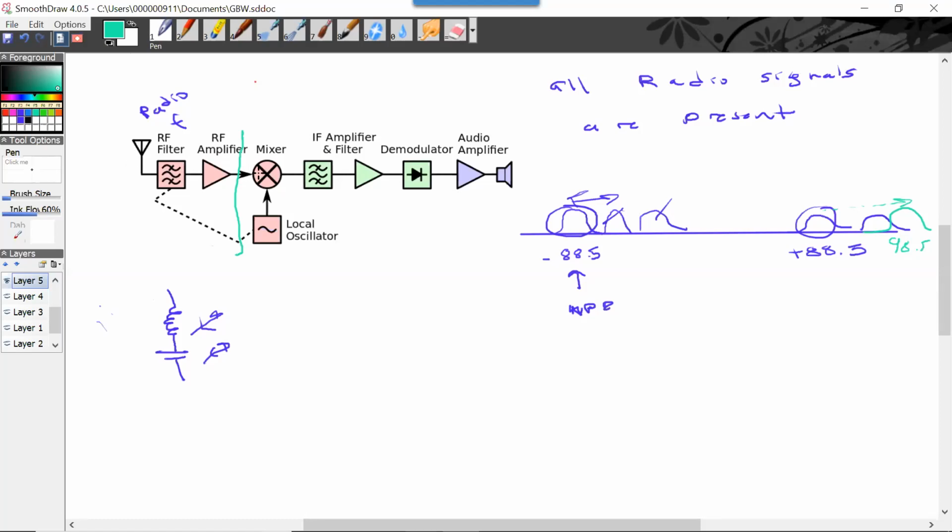And we put it through another mixer. And the thing is that the bandpass frequency here and the frequency here always make this. What they call it is heterodyning, meaning when you multiply a cosine by a signal, you get other frequencies. That's really all heterodyning is.